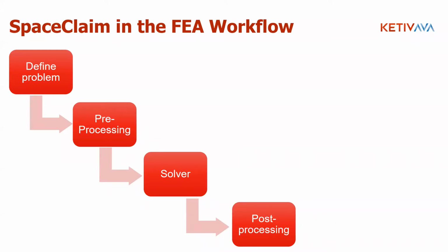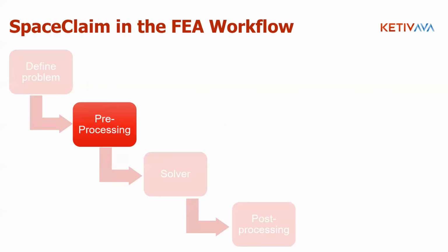And comes preparing our CAD geometries to perform what we have defined. So usually we need to apply our boundary conditions and loads. And that starts by taking that CAD geometry processing part and preparing it so that we can properly mesh it and turn it into a different type of model for the finite element method. And that's where Ansys SpaceClaim fits in.